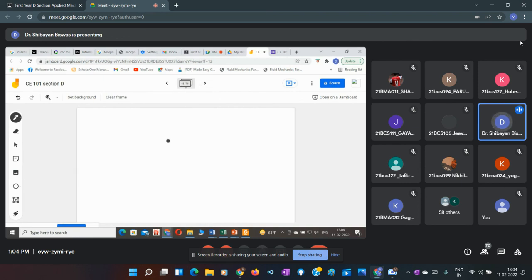So here the shear force diagram will be like this: this is L by 2, this is L by 2, this is L, and the reaction forces are acting like this. On this side it is minus W by 2, this is the datum line. Minus will be drawn below and plus will be drawn above. So this is plus W by 2 and this is also W by 2 from here to here, but with a negative sign. This is the shear force diagram for a simply supported beam if a concentrated load is acting at the center point.